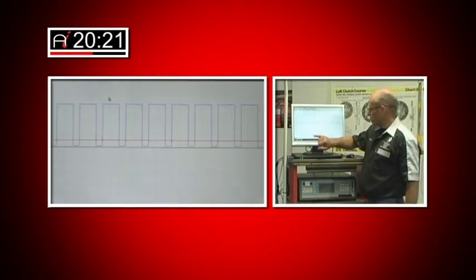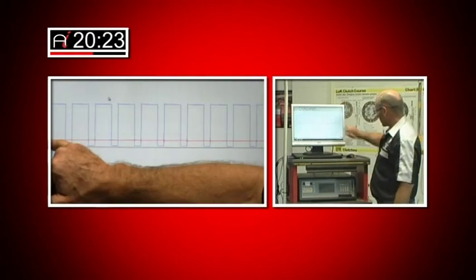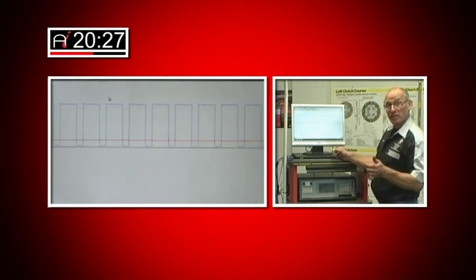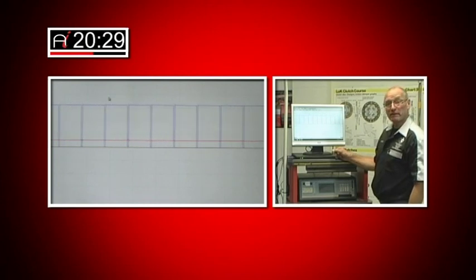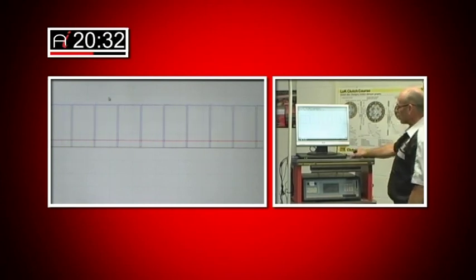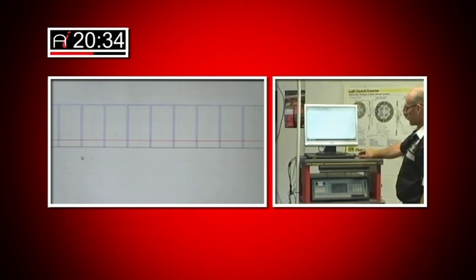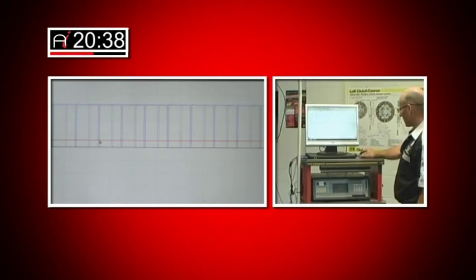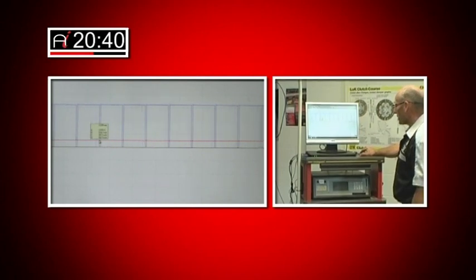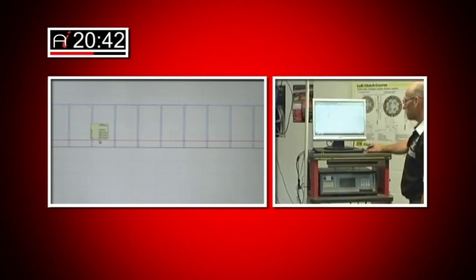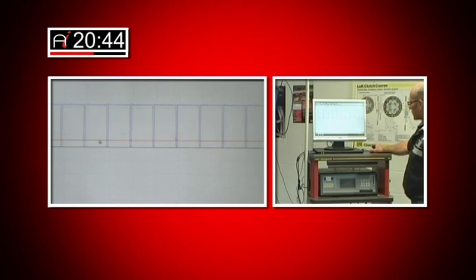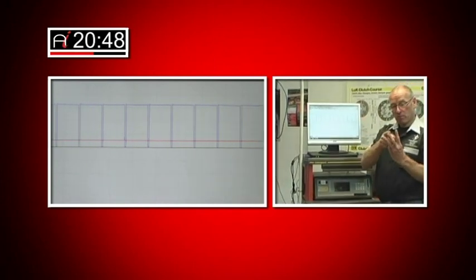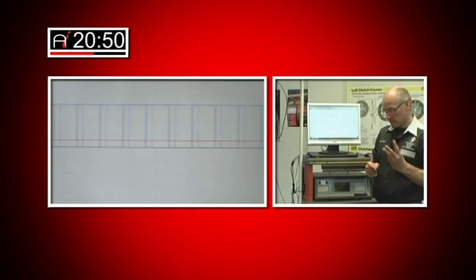The actual rail pressure voltage in red should have a plausibility value, i.e. key on static as we are now, of 0.5 of a volt. I can measure it with the cursor or with the marker, and if I left mouse, channel B, red, 518 millivolts, that's near enough. So the plausibility voltage, static, is correct. Output power ground, therefore, must be correct.